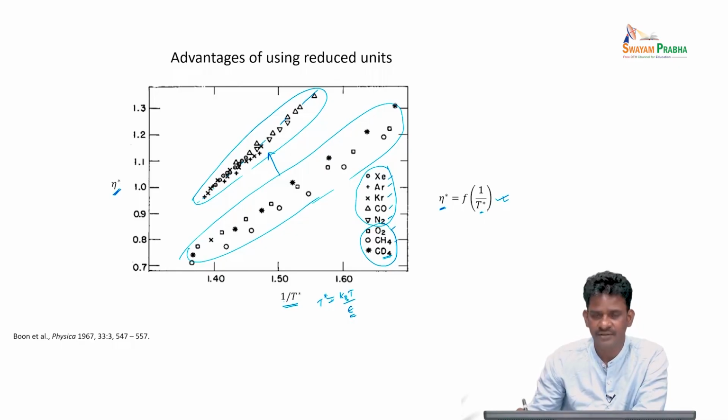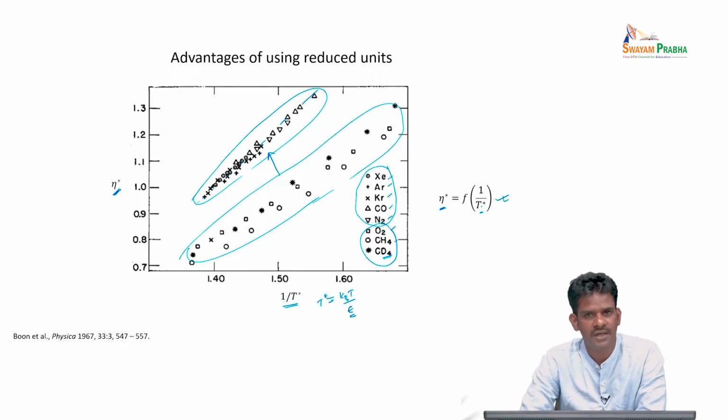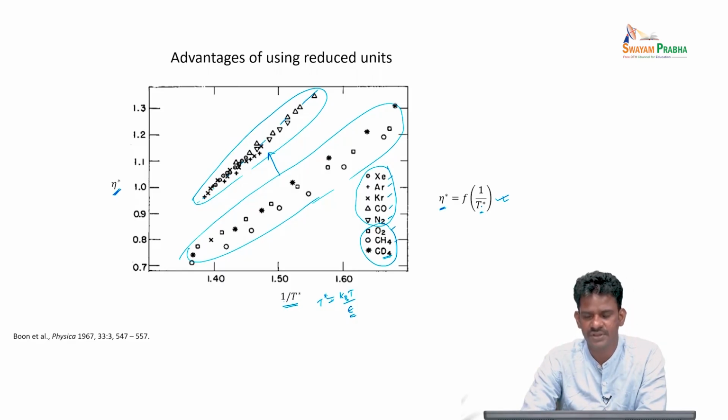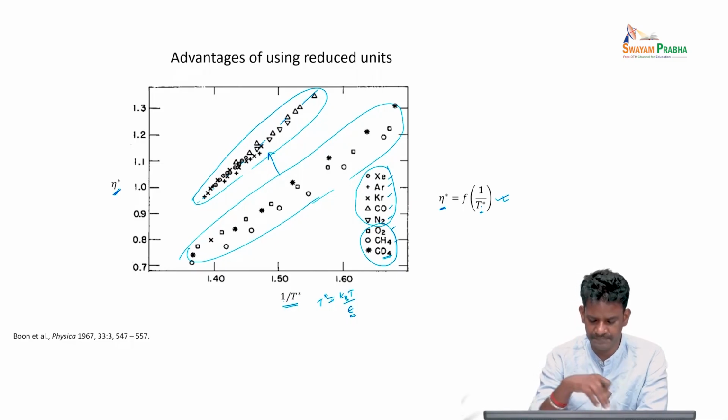So, you may have to add a little bit more additional parameters, so that they can also be written in terms of certain universal functions. So, the point I am trying to make here is that both compressibility factor or equation of state and transport properties could be expressed as a universal function of reduced parameters for a very large number of systems.